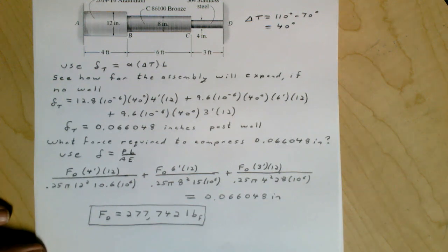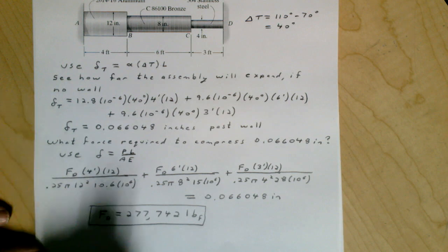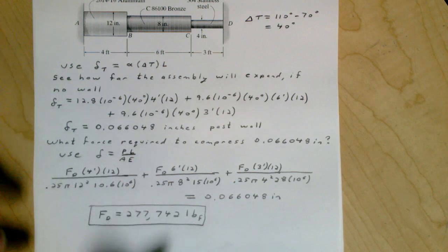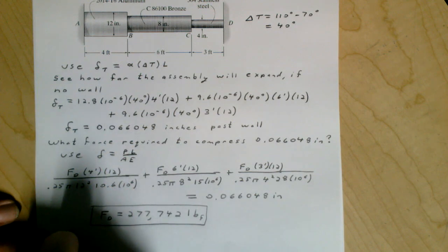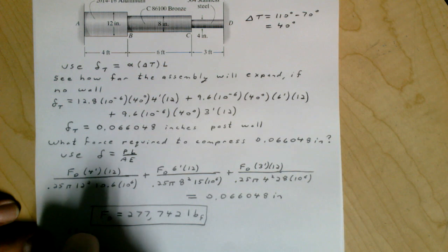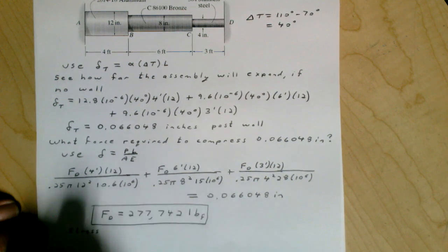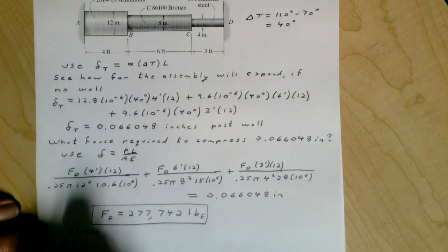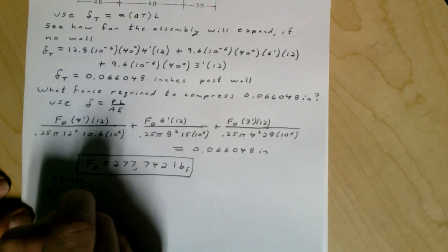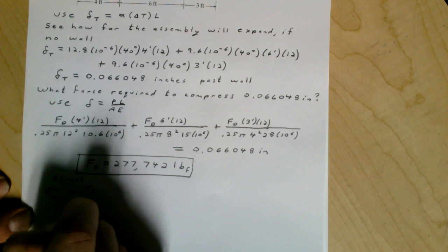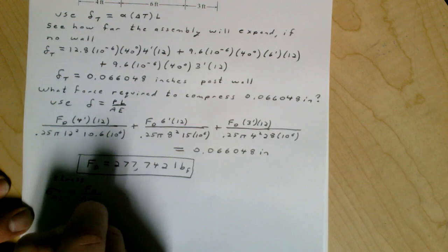Now, finally, they ask us for the stress in each part. And so for the stress, let's start with, say, the aluminum. The stress in the aluminum is going to be our force divided by the area.